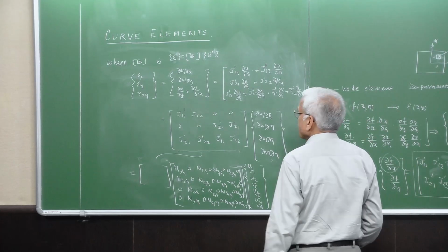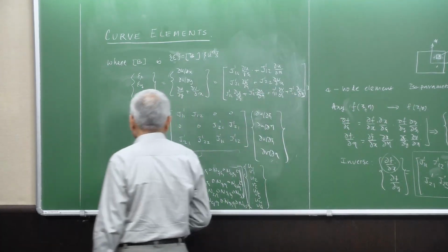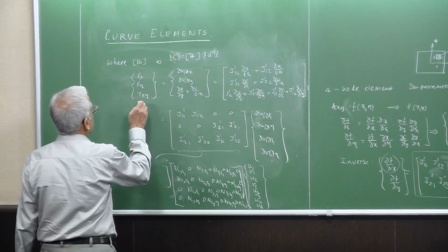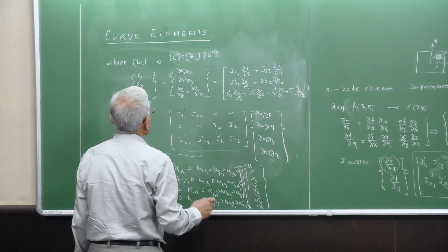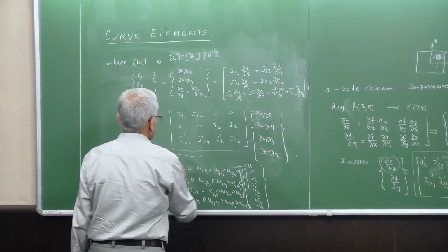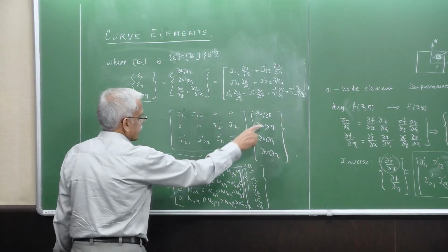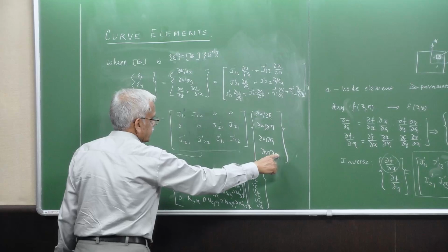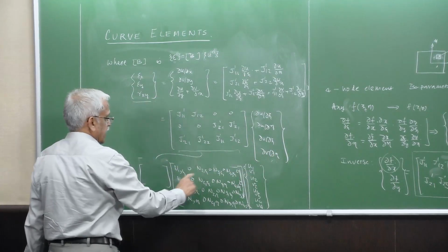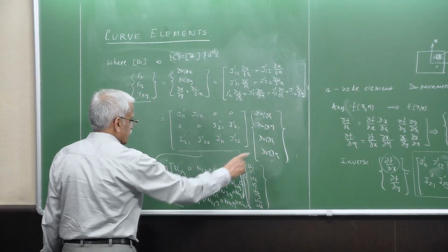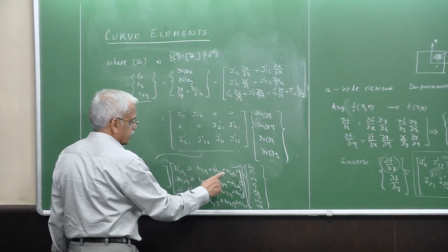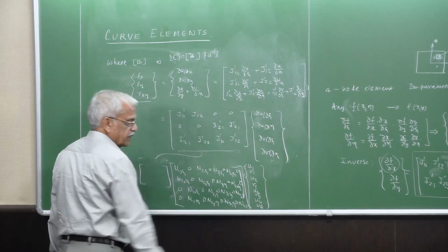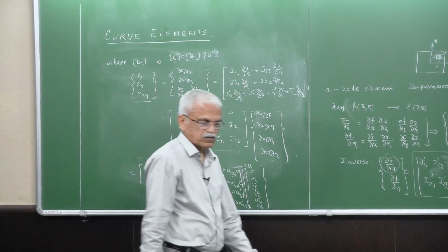It seems we have got lost here. We wanted the strains. Strains are written in this manner. So this is the derivatives with xi and eta, and finally these are converted to the derivatives of the shape functions with xi and eta, and then the nodal displacements.